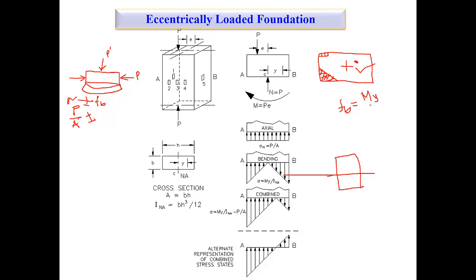FB equals My by I. What is Y? Suppose you take the stress at this portion, that is your Y.